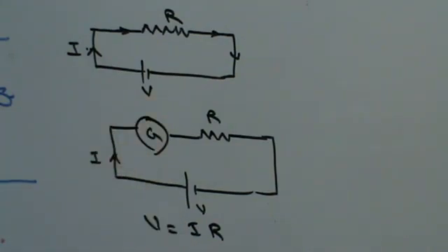What is an ammeter and how do I have to connect an ammeter? So do you understand this? In order to measure current in a circuit, I have to make sure that the resistance of the galvanometer is very small. Even if a small current is passed through the galvanometer, it should give you a deflection, and the coil in the galvanometer is very delicate and it gets easily damaged. So I should make sure that a large current does not flow through the coil of the galvanometer. The coil is made up of thin wire. If a very large current flows through that coil, the coil could get burnt.